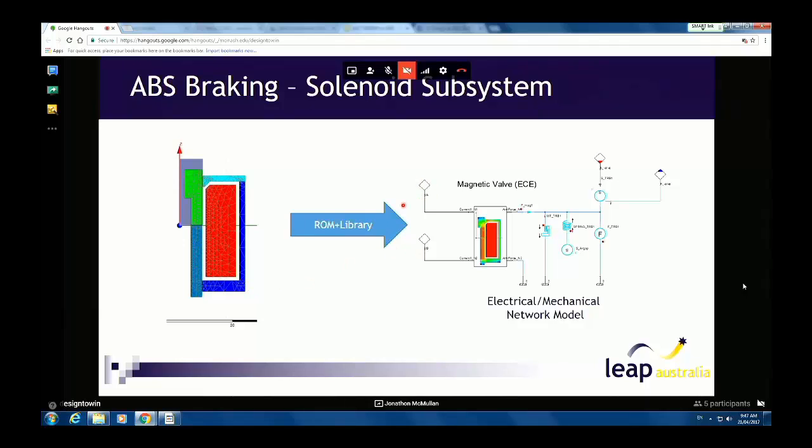We then pushed the export button, and we get this extra block here. It has our two input terminals. It has a reference point for one end of the arm, which is at the bottom, and then the amount of applied force is exposed at the top. So this is a full nonlinear system. Usually developing a reduced-order model like this takes a long time. Because the process is automated, it's very convenient and just about anyone can do it.